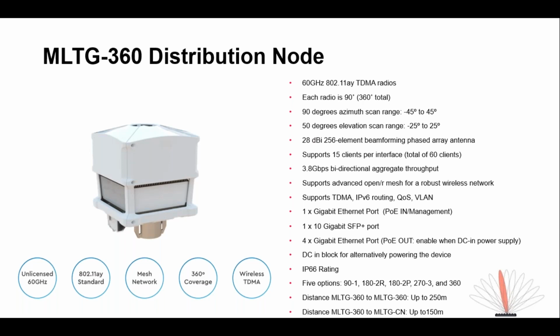That's kind of how beamforming works, where you've got multiple beams you could scan to and talk to various clients, but the actual specific beam you talk to is narrower. That's how we get the gain way up, because there's no way a 28 dB gain antenna would have 90 degrees of coverage. Instead, the beam itself talking to an individual client is narrower than even 5 degrees. And that's where all that gain is coming from.